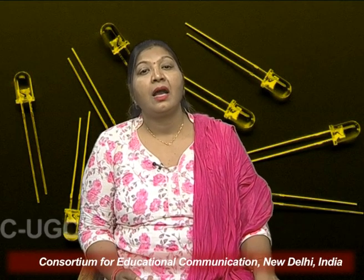And if we try to run the current the other way, with the p-type connected to the negative end of the circuit and the n side connected to the positive end, the current will not flow. Negative electrons in the n-type material are attracted to the positive electrode, and positive holes in the p-type material are attracted to the negative electrode. So no current flows across the junction because the holes and the electrons are each moving in the wrong direction.